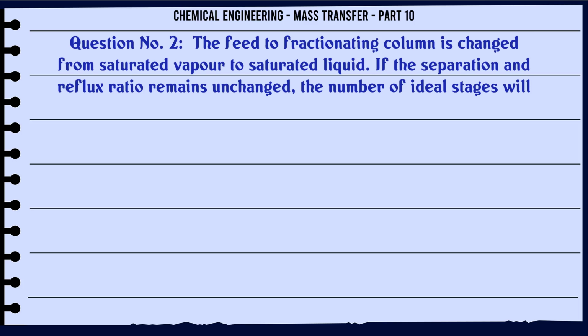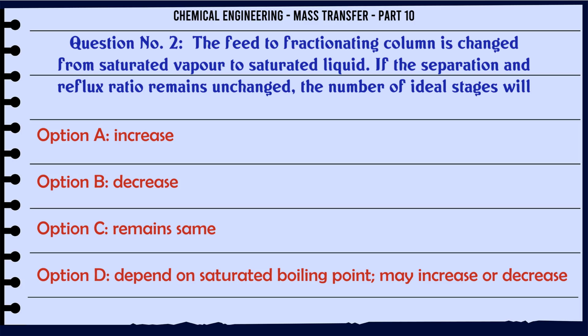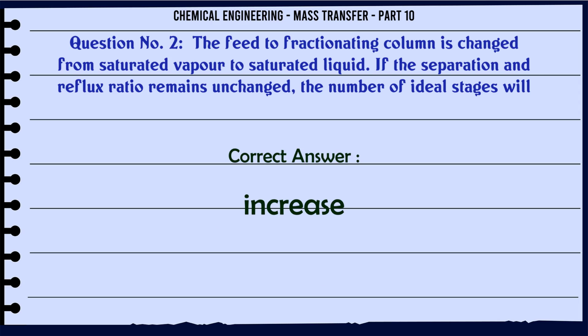The feed to fractionating column is changed from saturated vapour to saturated liquid. If the separation and reflux ratio remains unchanged, the number of ideal stages will A. increase, B. decrease, C. remains same, D. depend on saturated boiling point, may increase or decrease. The correct answer is increase.